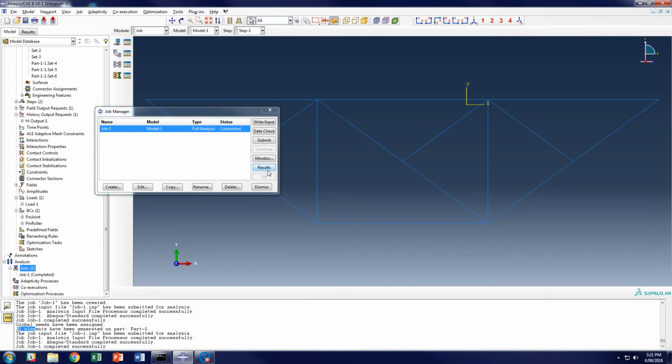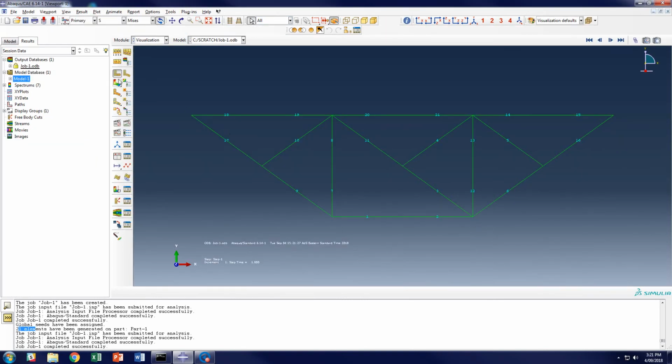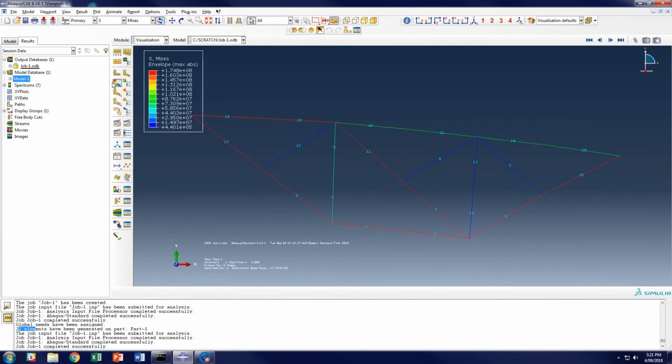Now, there may be questions regarding when do we know our results are accurate. The question is, what level of accuracy over the value of concern is important for you as the engineer? So we've gone from 169.8, so call it 169 megapascals, and now we have a stress of about 175 megapascals. That's a change of 5 megapascals, which may make a difference for this system of whether we want to keep this result or not. The yield stress for a mild steel might be in the order of 250 megapascals, and we're relatively close to that.